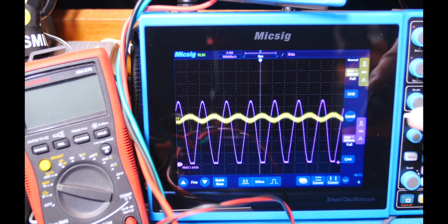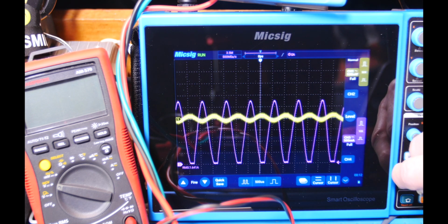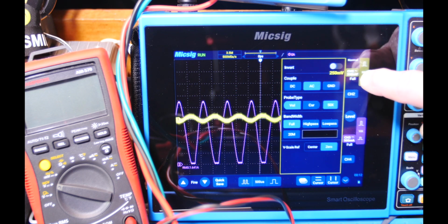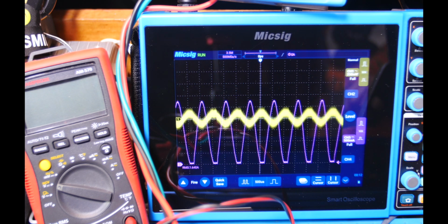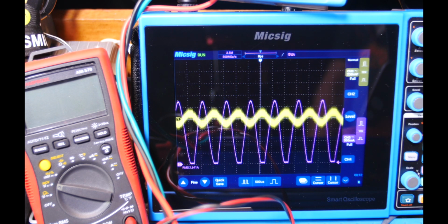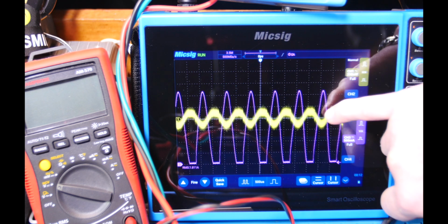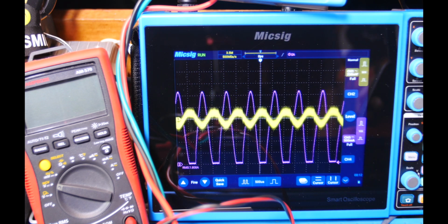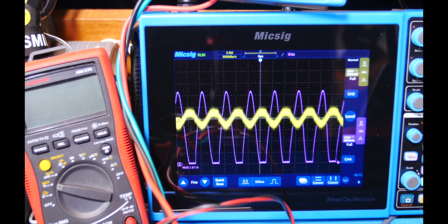All right guys, I've got the probe AC coupled and it's 500 millivolts per division. So let's go to, whoops, wrong one. Let's do this guy, 250 millivolts per division. Okay, that looks sinusoidal, not bad ripple. But our signal is really low right now. Now let me increase my generator signal, and you notice something starting to happen. See how there's a shift right here in the power supply? It's a sharp change, and it happens when this ripple comes up right here.